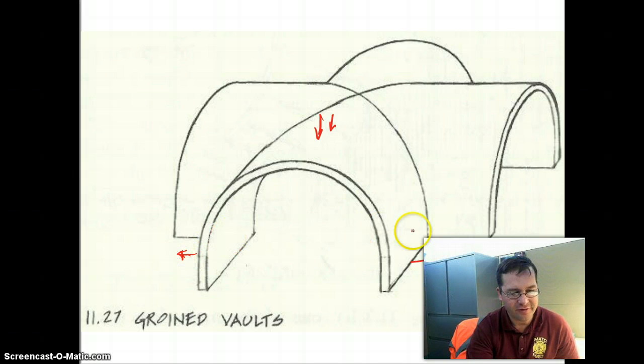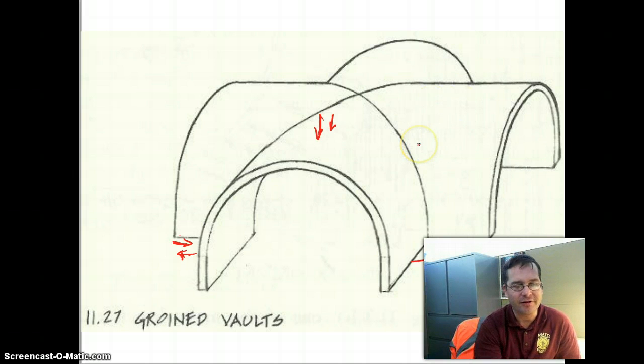That, however, is resisted by the base of the intersecting arch, so that this is inherently stable, and the only way to collapse this is basically to have a compression or tensile failure in the materials of the arch. So you don't see this real frequently in modern commercial construction, but in the days when our knowledge of building materials was very limited, this was common, typically in cathedrals and construction of that type, where they had to span great distances with very limited materials.